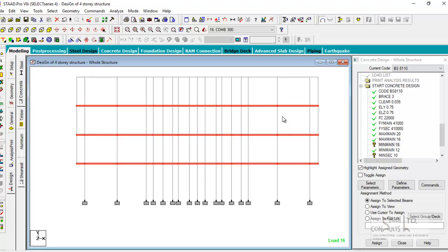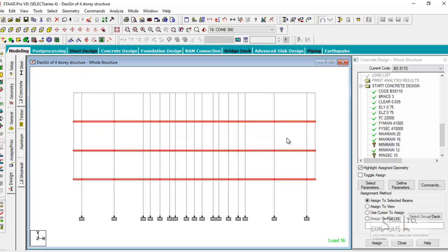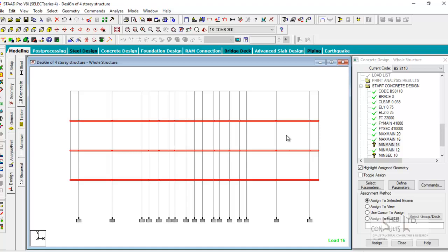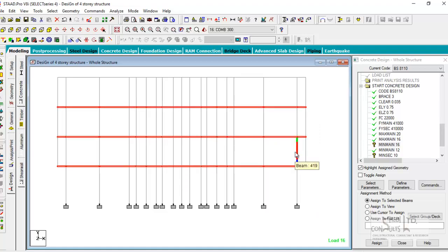So you find out that the capacity of the concrete, for an FCU equals 30, has significant strength against compressive load. So it's except you have biaxial or uniaxial bending that makes the stress distribution on the concrete cross section change and become highly indeterminate, that your reinforcement sizes will not have to be increased. And note, because of the design requirement and the use of design charts in column design, the sizes of reinforcement on each face have to be similar. So they have to be the same number of reinforcement sizes on each face.